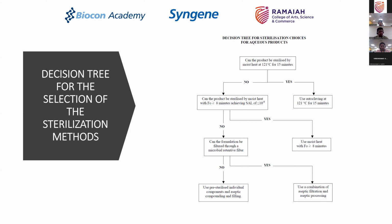In that, you will apply this formula to say that when my F0 value is greater than or equal to 8 minutes, which means I need a time of more than 8 minutes to achieve an SAL of less than 10 to the power of minus 6, then I will still be able, by changing the condition, to apply the terminal sterilization technique, right? Yes. So that is what you have to apply here.